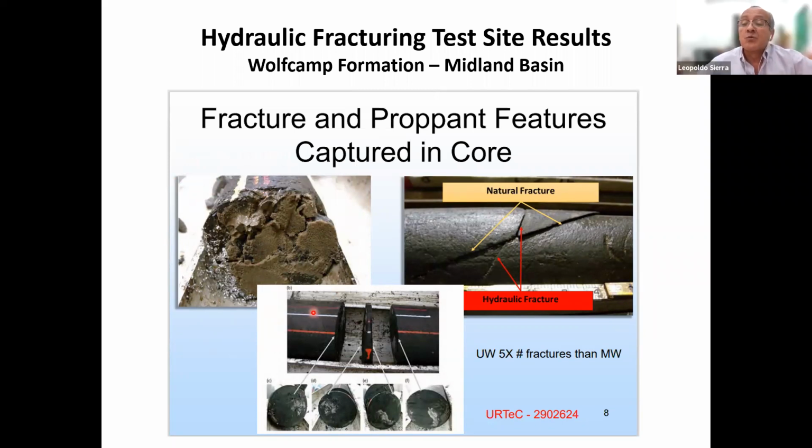They're showing a picture where the proppant concentration is very big here. It's like the fracture was totally packed with 100 mesh proppant. But the problem here is that the concentration of the proppant is very high. It means that the concentration was really magnified here by the breaching effect. It's not really the typical packed proppant. If we're packing the proppant, normally the concentration of proppant needs to be really smaller than this one.